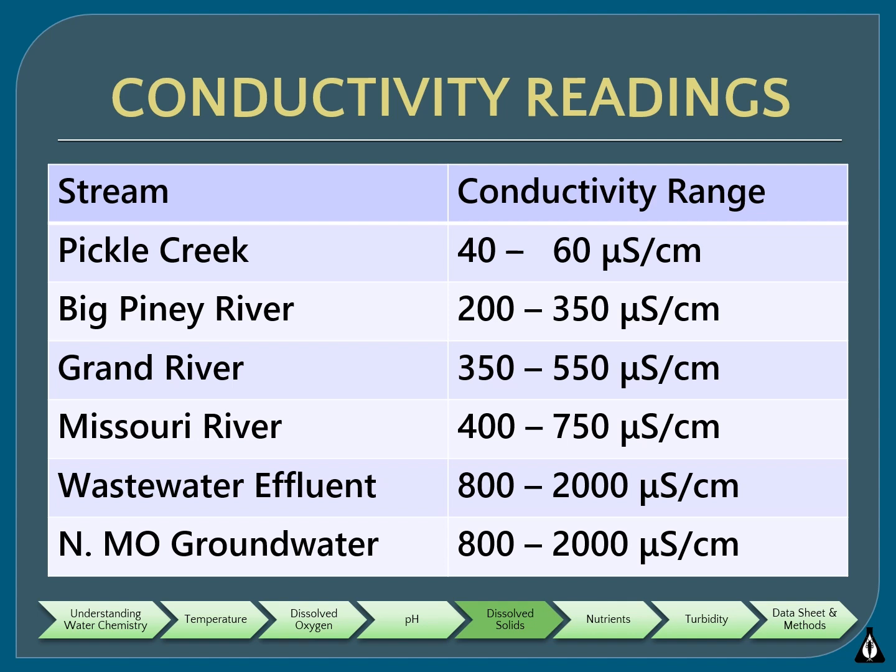In general, the larger the water body, the increase in the surface area of the watershed, therefore an increase in point and non-point source impacts that could potentially be influencing the conductivity of the stream. For example, Missouri River is a very large watershed. A lot of point sources and non-point sources are coming into this stream. Therefore, the conductivity readings and ranges of that are going to be higher simply because of the size of the watershed.